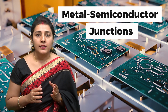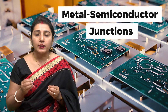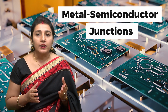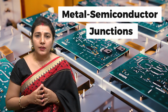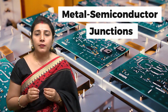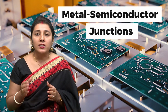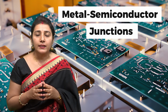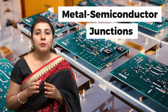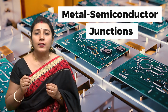In many cases, we wish to have an ohmic metal contact with the semiconductor, having linear IV characteristics. IV is current voltage characteristics, in both biasing directions. For example, the surface of a typical integrated circuit is a mesh of p-n regions which may be contacted and interconnected. It is important that such contact be ohmic with minimal resistance and no tendency to rectify signals.